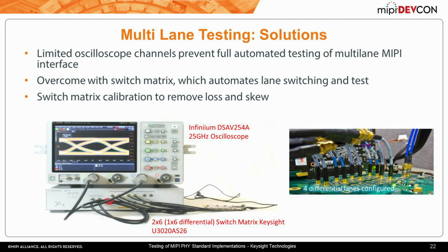And we're going through a switch that has some additional loss. We've essentially extended the length from our DUT to our test environment significantly, and we now have some loss that we have to compensate for. So you can do that in today's modern oscilloscopes, they actually have de-embedding capability, and that helps to compensate for this additional loss. Now what you want to do, though, is make sure that you've measured that so you know how much loss to back out from your measurement.